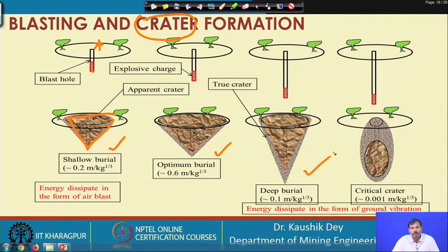What we did was insert the explosive in a hole and carry out a blast, then increase the drilling length and carry out the blast, then further increase the drilling depth and carry out the blast. So, basically the same quantity of explosive is blasted, placing it at a deeper and deeper position.